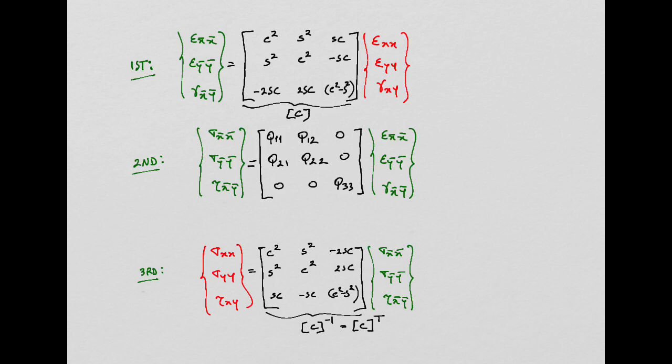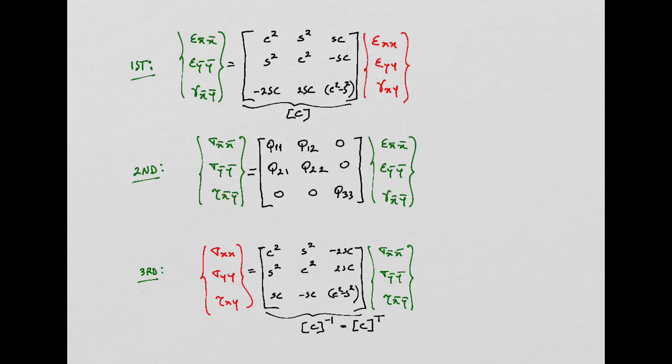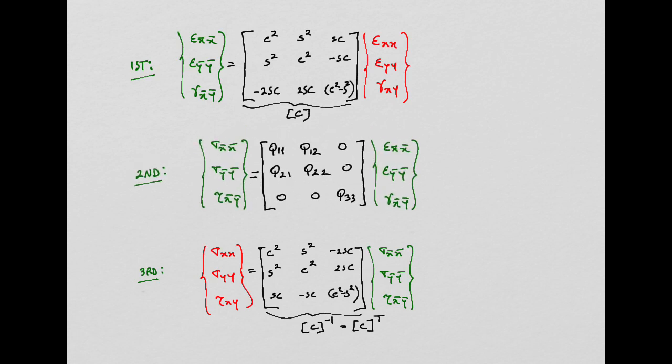Now, let's discuss one important thing here. You are used to doing this process for an isotropic material, which is not a composite material, in one step. If I give you the strain tensor in the global coordinate system, you just use Hooke's law to get the stress field.